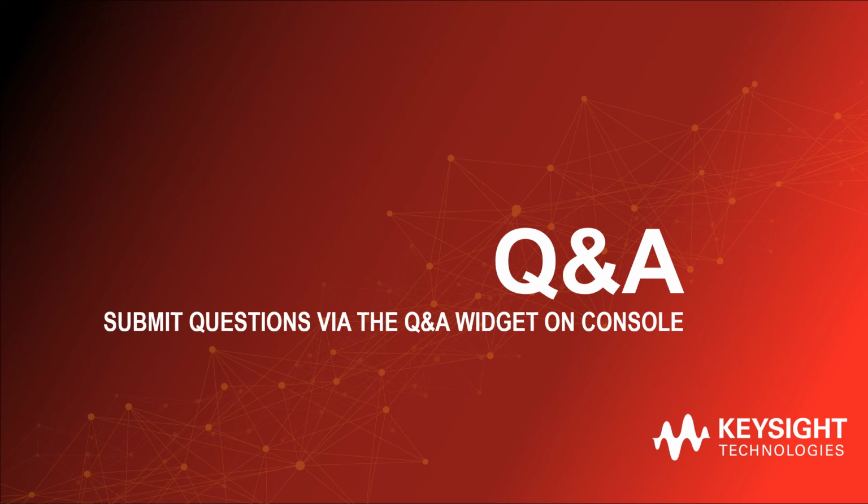The most suitable commercial equipment that can be used in this kind of development would be a high bandwidth arbitrary waveform generator, very similar to Keysight's popular AWG, for instance, the M8199A, which is a very high bandwidth 4-channel arbitrary waveform generator, which has a pretty high sampling rate per channel at 256 gigasamples per second, and DAC resolution of 8 bits. It can also do very complex signaling like 4 level, 8 level, or even 16 level or more.